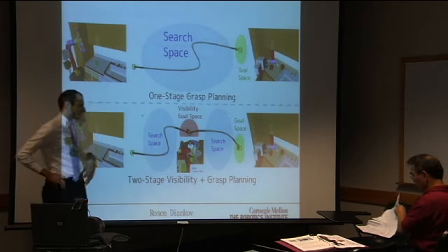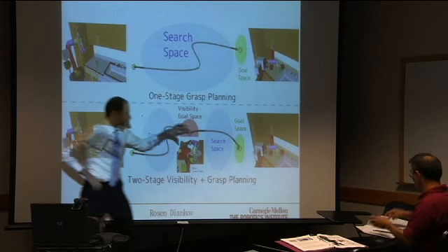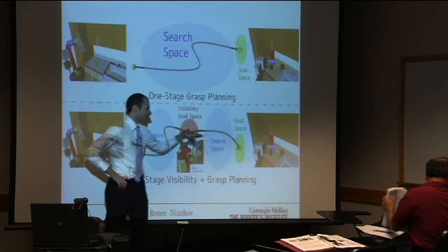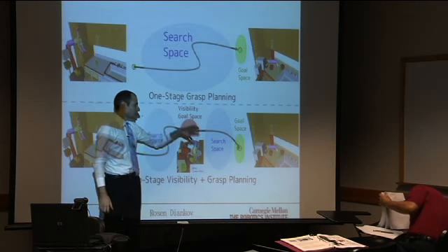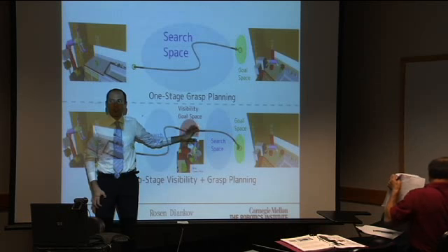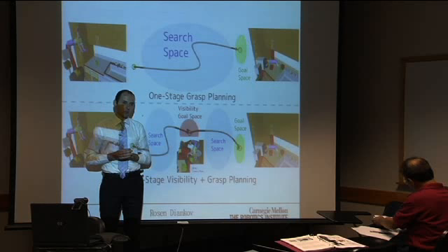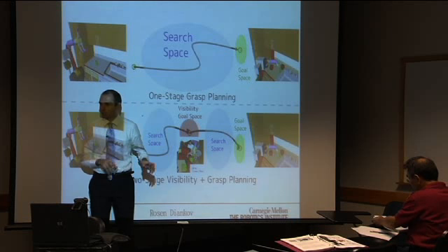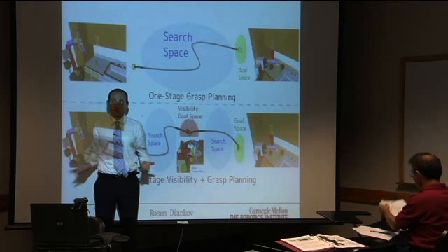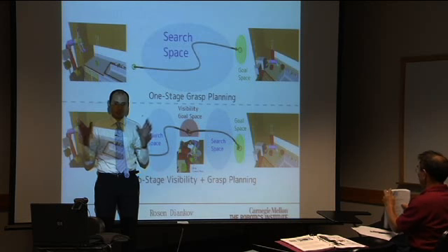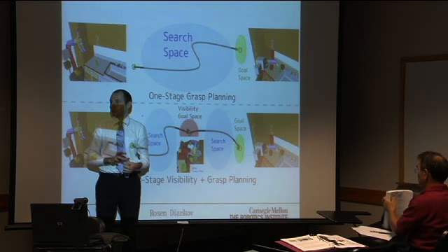Oh, okay. I see where you're coming from. The visual servoing systems that you're discussing, the way I see it, fit into the second stage. You already have the object in the sensors, and now you're concerned with getting closer to it while tracking it. Maybe something can change in the scene, there's dynamics, maybe the object can move itself. You want to compensate for it, which is why people do visual servoing. In the end, you always want the object as accurate as possible. That's why even when you get really close, you track it.